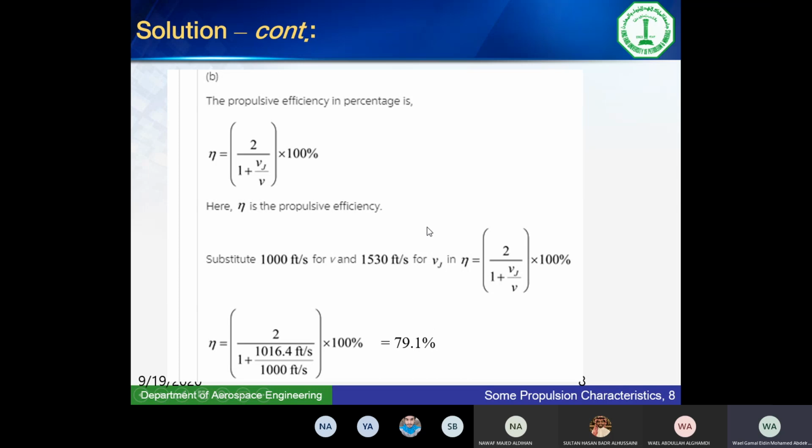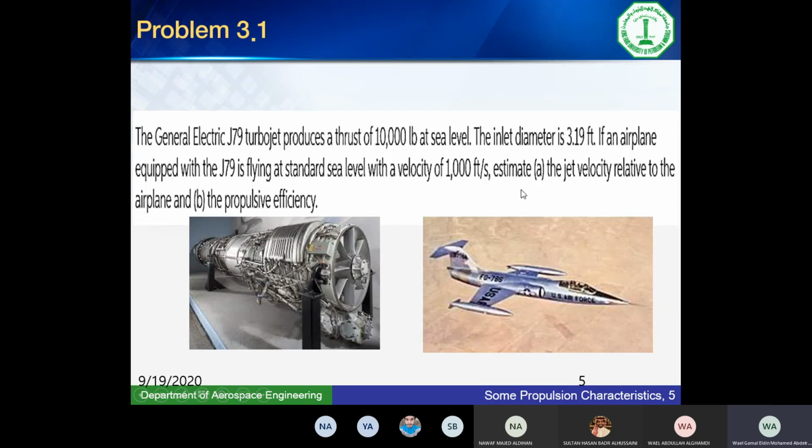Thank you. So efficiency for a turbojet is reasonable for high speeds. So turbojets are on fighter aircraft, for example, the ones that fly close to the speed of sound or even faster. Turbofans have better efficiency when the speed is slightly lower, let's say 0.8 or 0.7 Mach number.